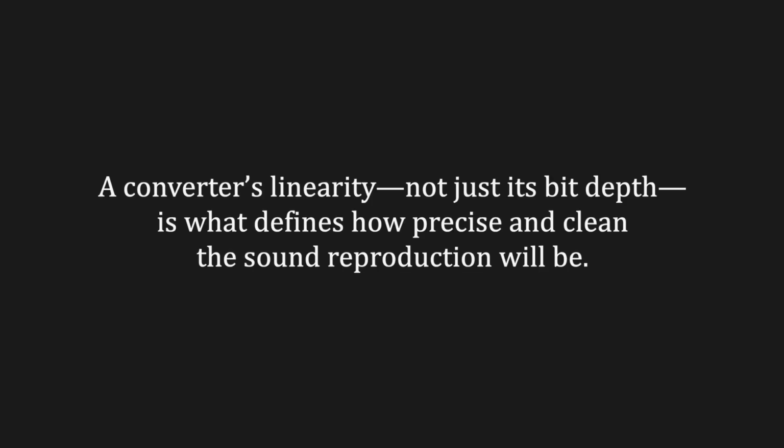Linearity tests measure how accurately a converter reproduces different levels of sound. Linearity means the output signal's amplitude correctly matches its digital input value. Any nonlinearity causes distortion. Traditional ladder-type converters often show this problem because of tiny bit weighting errors, which can increase with temperature changes, stress, or aging. Some DA converter chips include built-in calibration tools to help manufacturers adjust and improve accuracy. Ultimately, a converter's linearity, not just its bit depth, is what defines how precise and clean the sound reproduction will be.